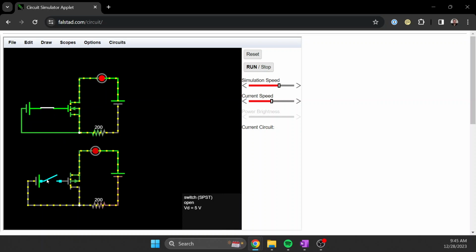So that is the significant difference between N-channel and P-channel enhancement MOSFETs. They're extremely useful. We're going to talk about them later. And a lot of times when people talk about MOSFETs, they're specifically talking about these. The depletion mode MOSFETs do have their place, but they're a little bit less common. These are really the default ones people are referring to.